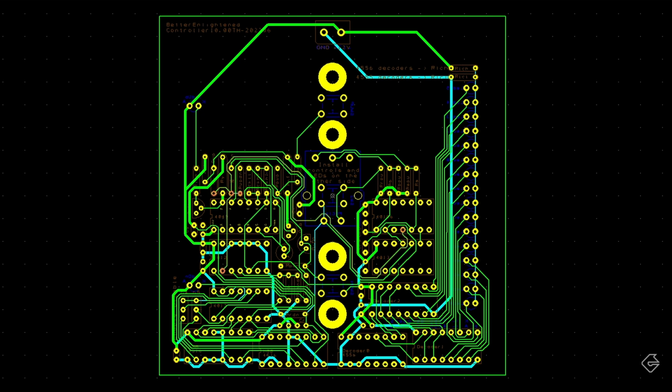And the last one was direction. Here's the final net that is disconnected. Let's add in a trace to connect this as well. Nice, all connected. So now that we've completed the layout for the rotary encoder and the buttons, we've also made sure that they're connected together and to the logic center. We're almost nearly there. The next thing we gotta do is look at the power and ground connections.